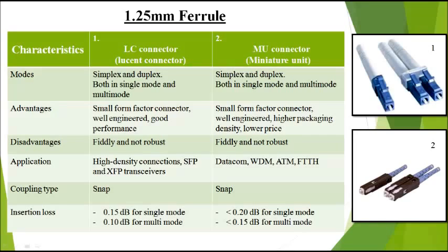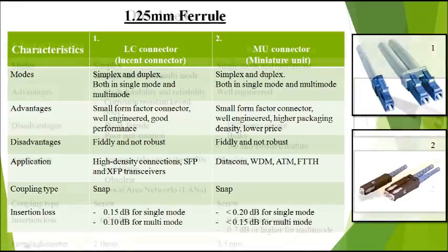MU connector is widely used in datacom, WDM, ATM, and FTTH application. MU connector uses snap type of coupling. The insertion loss of MU connector is less than 0.2 decibel for single mode and less than 0.15 decibel for multi-mode.